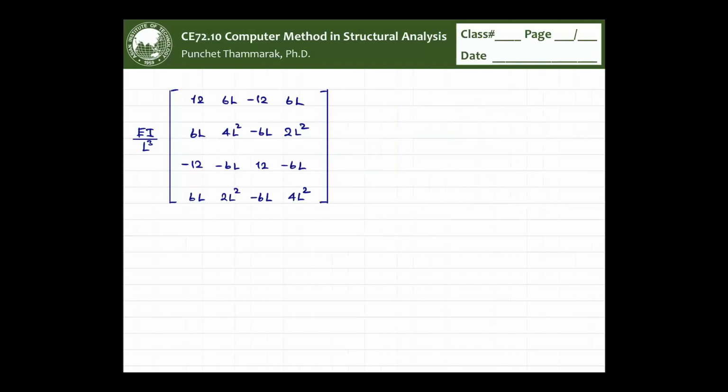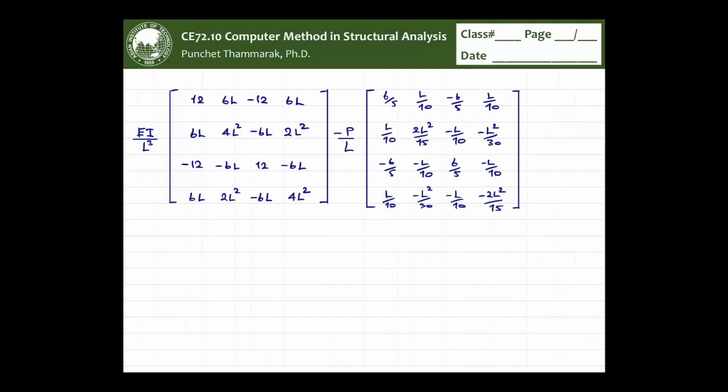Actually, you will have a system that combines many structural members, but if we just consider one individual structural member for now, the right hand side will be what? All zero, right? We set up the equilibrium equation to determine the buckling load. External force, we set it to 0. So the right hand side vector is 0 now. Everything here is multiplied by the deformation U.